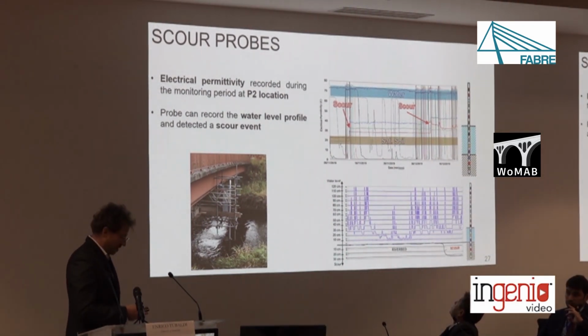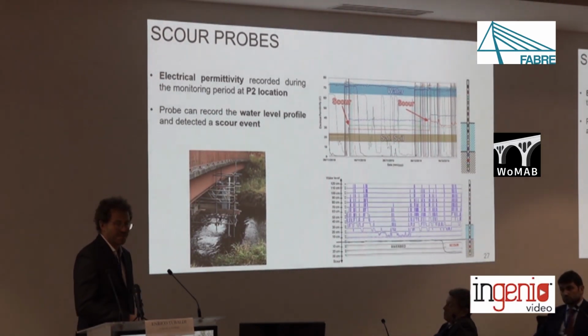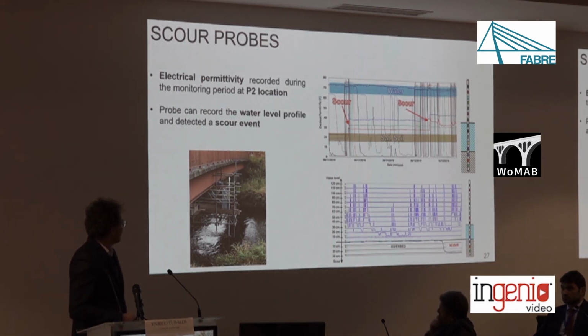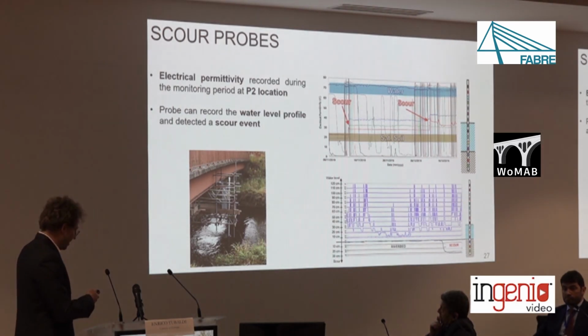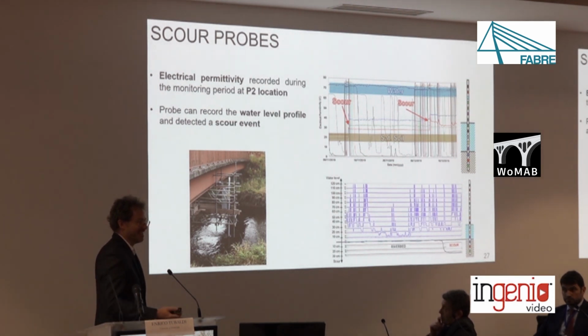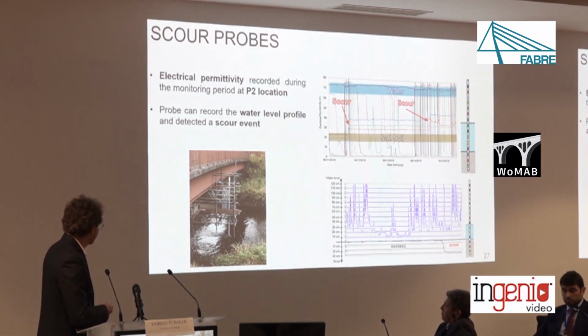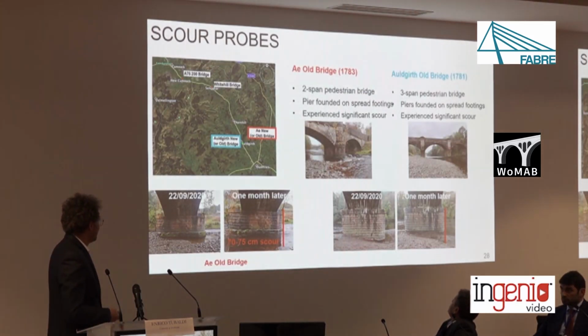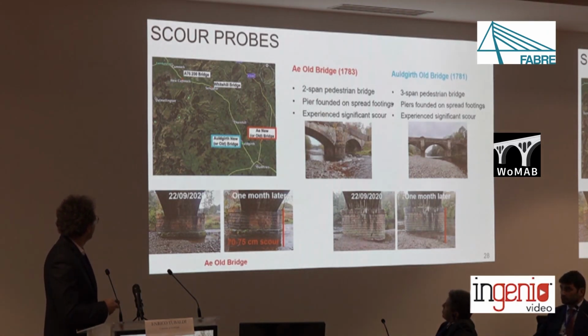And so, yeah, the probe seems to work fine. However, it is quite expensive to maintain them. You see, they require a very big scaffolding to be installed. This is mainly for accessibility and health and safety issues rather than for other reasons. However, you can imagine that this scaffolding can attract debris, which is a killer, and it can exacerbate the problem of scour. So I'm personally not a big fan of these scour probes, even though we are going to install more of them at 2 other nicely listed bridges south of Glasgow.